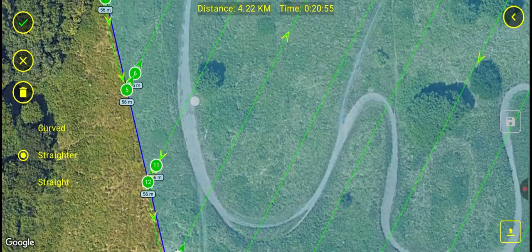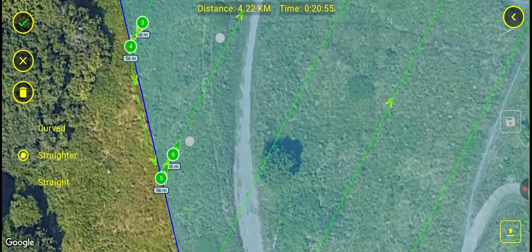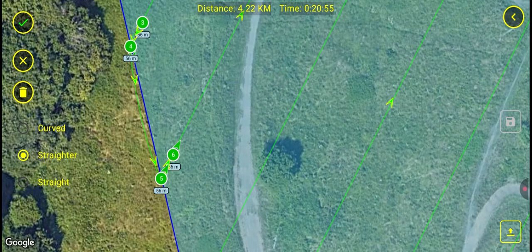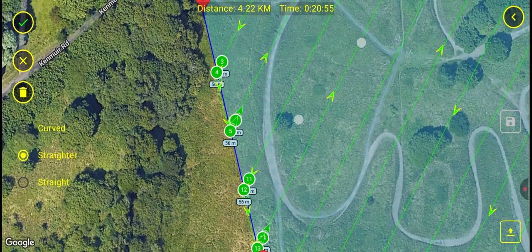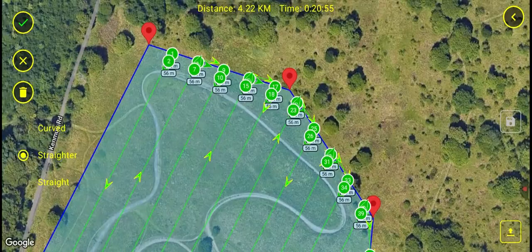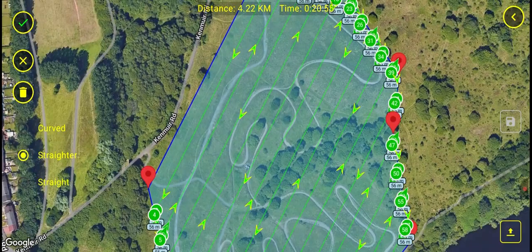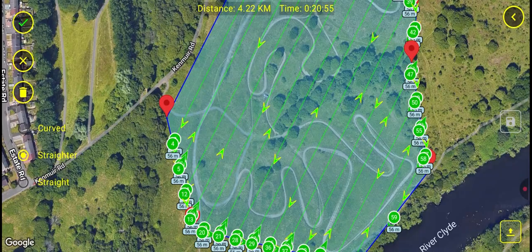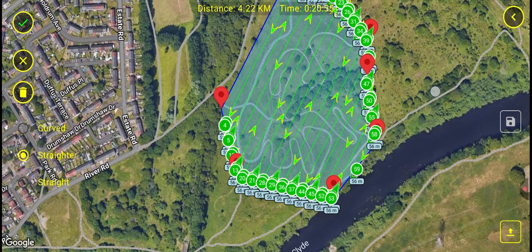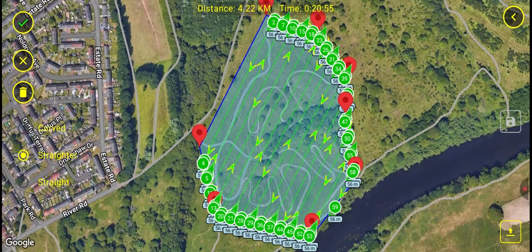I have added more waypoints, and the Bezier curve is restricted to the 4 at every corner, and then it flies a straight line to the next set of waypoints. Hence you get your lawnmower path. Now there's an advantage doing it this way, which I'll explain later, but I've tested this, it works well, and to be honest, I recommend you use this method.